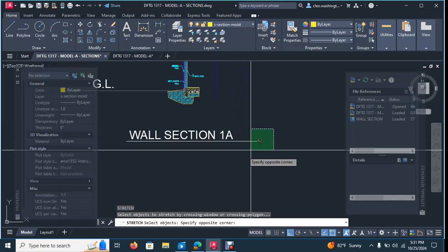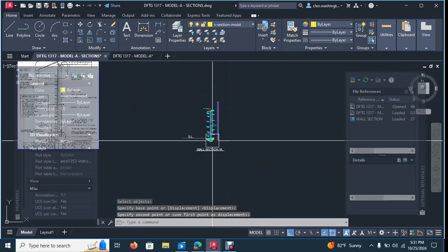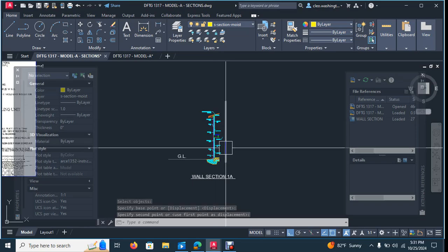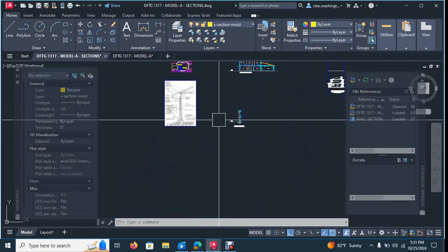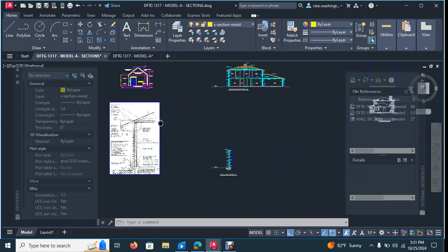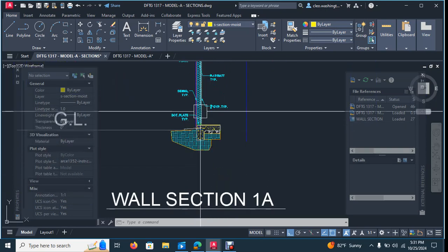And that is on a 0 print layer, so it won't print, but we need to denote what that is, all right? So next we'll go ahead and we'll draw the wall section at the brick portion of the building, which is essentially going to be the same thing. We'll just copy this wall section over and we'll actually apply brick.